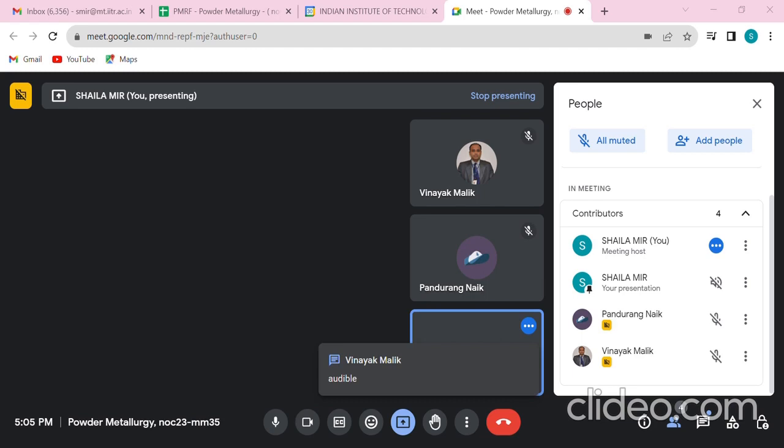During mechanical crushing, there are different types of forces that will be exerted on the particle. So, for example, we have a powder particle and we wish to crush it, and we can crush it by enforcing various types of forces, which include pressure. Like we will try to act various types of pressures on it so that it can be milled. We can exert a friction force, which will be through these plates on this powder. We can exert an impact force, which will be to push a heavy object against this particle and it will be broken down. Or we have a cutting action or a shearing action, which helps in cutting of the particles to the smaller particle sizes.